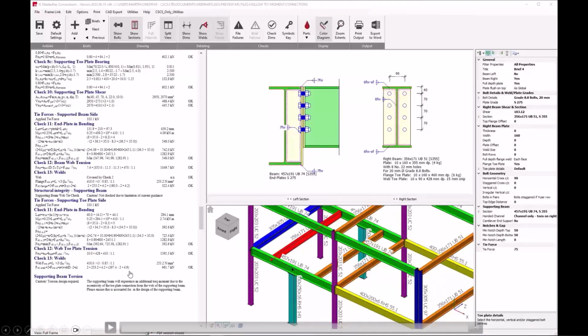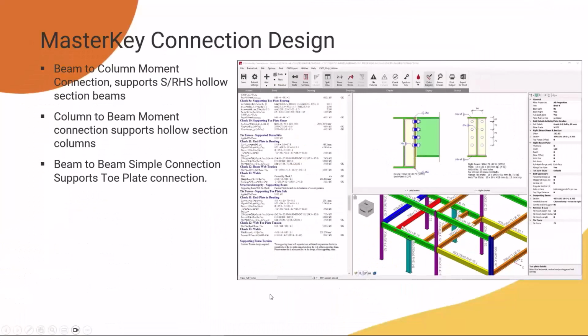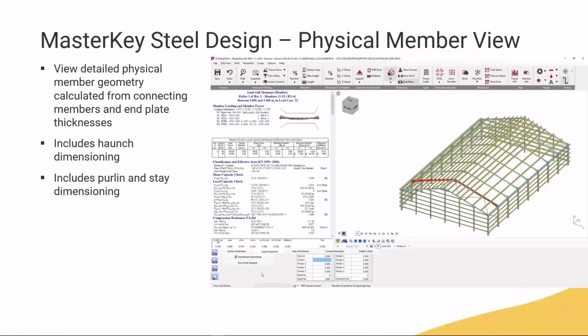This could be a standalone connection. We don't really know if it was a standalone connection, where the connection is along the length of the member, what the end conditions are. So it's not something that can be calculated at connection design time, but it's something for the designer of the beam to be aware of, that this is being used. So that's a really important caveat to put into place there. Okay.